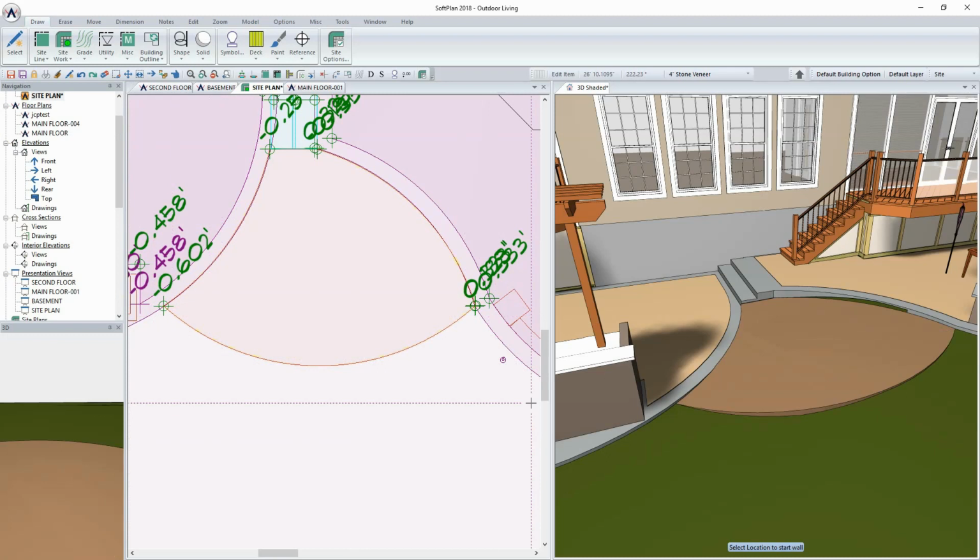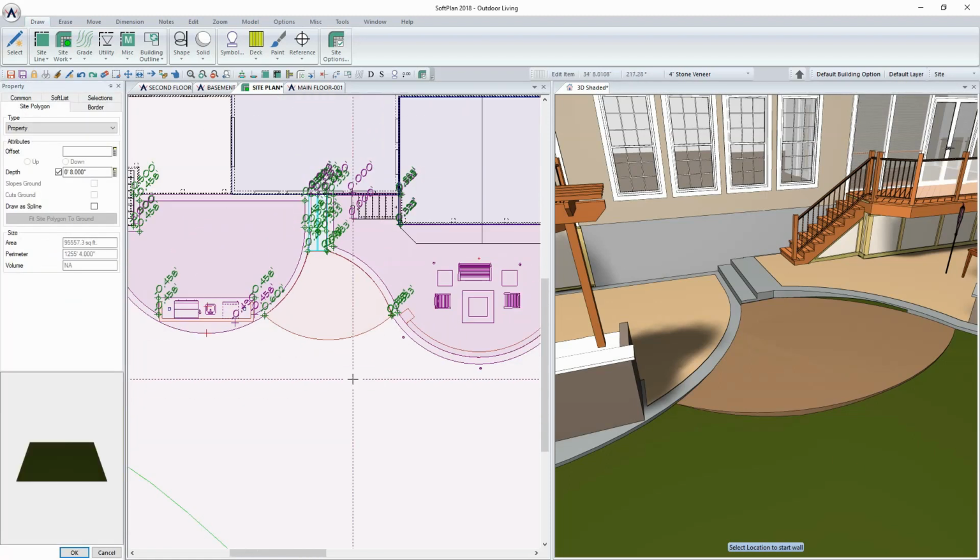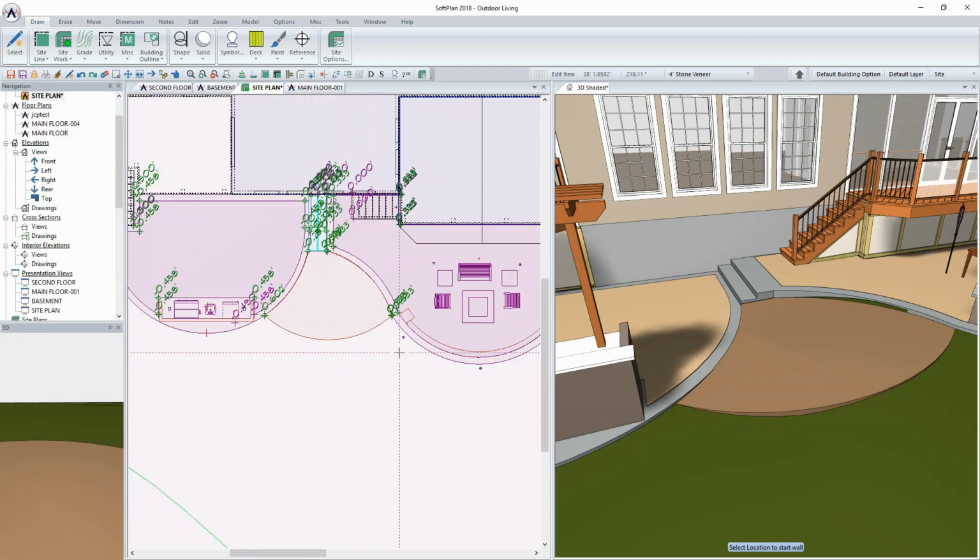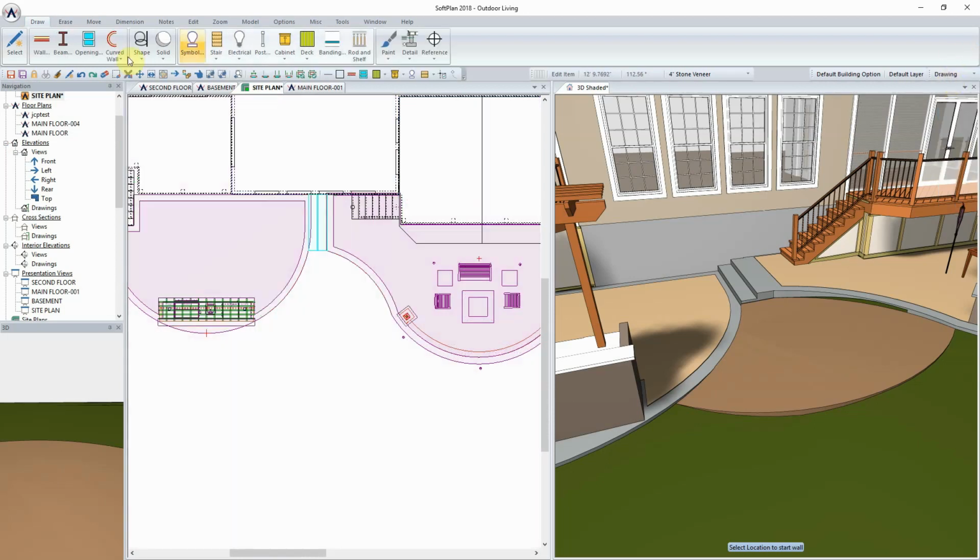This may necessitate, as I'm beginning to work with this, going in and adding some retaining walls just to help with erosion and so on. And I'm going to go back to using some of the walls that I defined already. And so as I change into drawing mode, the drawing mode will give me the access to be able to sketch the wall. This is going to be a little bit of review, but as you'll see, when I change into the drawing mode to sketch walls, I no longer have access to the visibility as far as where the planting bed is.